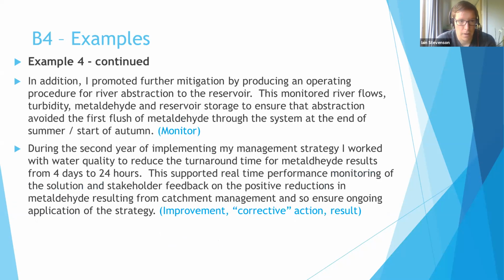In addition, I promoted further mitigation by producing an operating procedure for river extraction to the reservoir. This monitored river flows, turbidity, metaldehyde, and reservoir storage to ensure that abstraction avoided the first flush of metaldehyde through the system at the end of the summer, start of the autumn. So that explains the monitoring side of this problem.